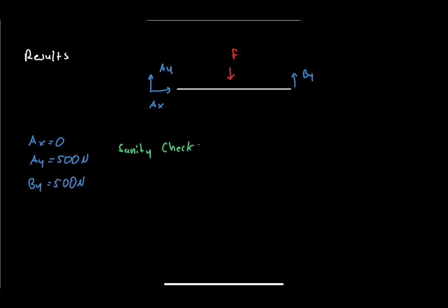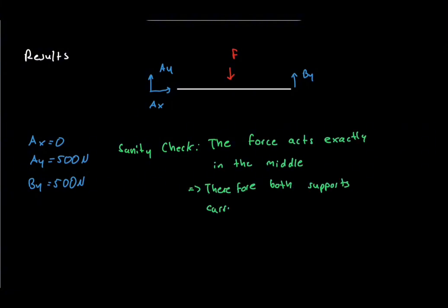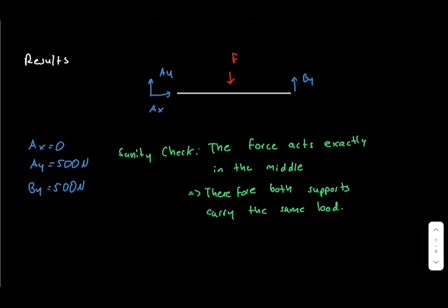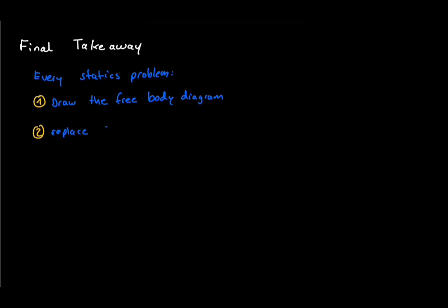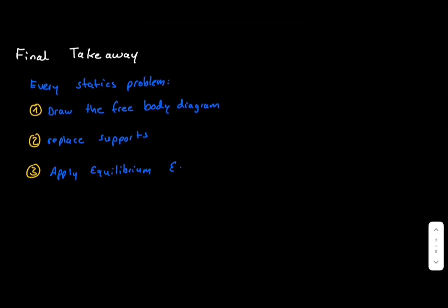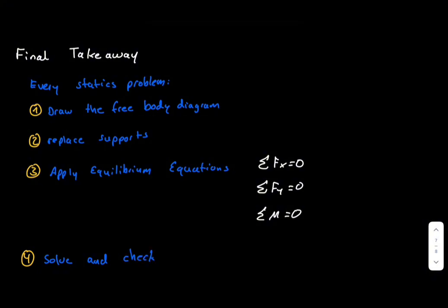Before finishing, let's perform a reality check. The load acts exactly in the middle of the beam. Therefore, it makes sense that both supports carry the same load. And this brings us to the most important lesson of this video. Almost every statics problem follows the same 4 steps. Draw the free body diagram. Replace supports by reaction forces. Apply the equilibrium equations. And finally solve and check your result. Master these 4 steps, and you will be able to solve a large number of engineering problems.